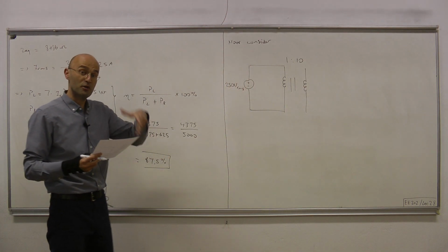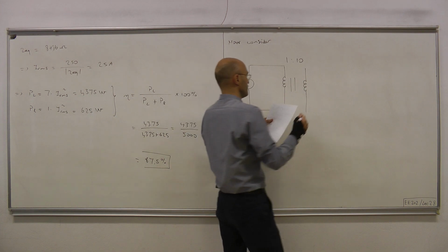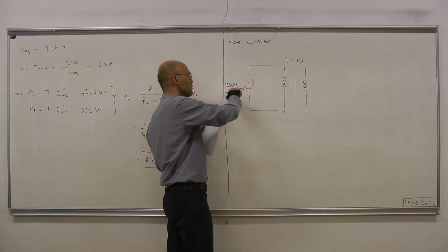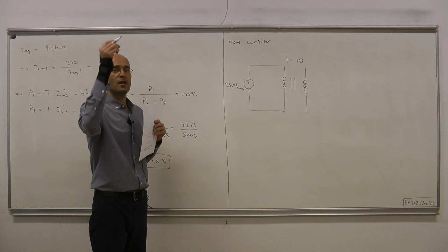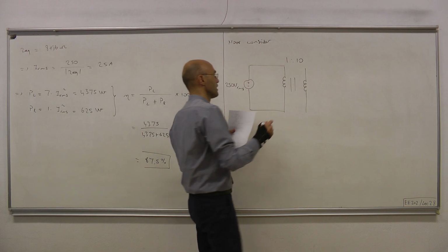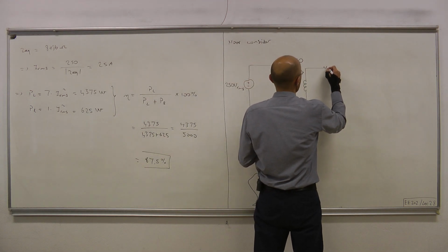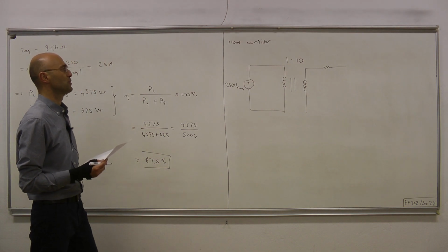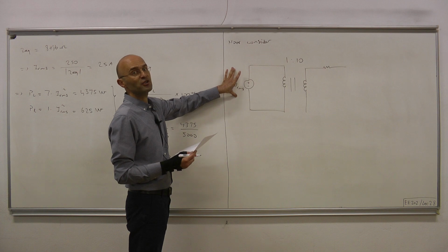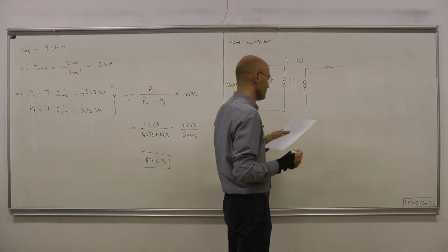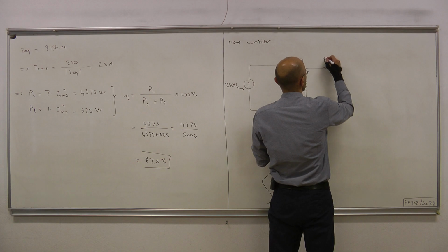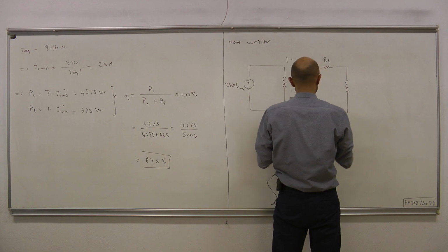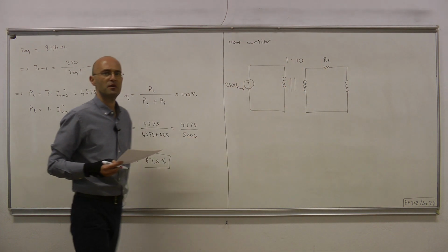Well, in practical applications, it's much, much higher than 1 to 10. But for simplicity, let's make this voltage from 250 volts to 2500 volts, okay, by using the following transformer. And then the power is now transmitted through the transmission lines at a much higher voltage, 2500 volts. This is RL, which is 1 still, and then once we reach the city, once we reach the customer end,